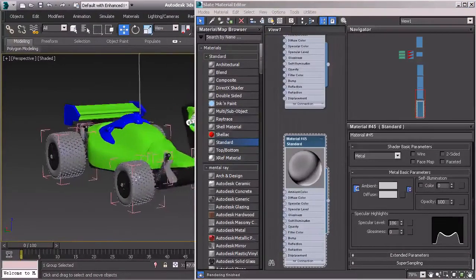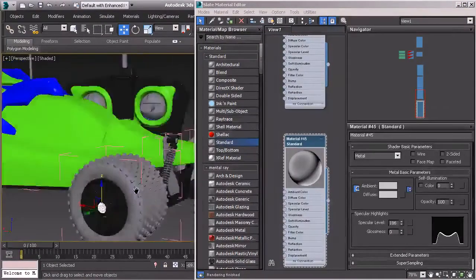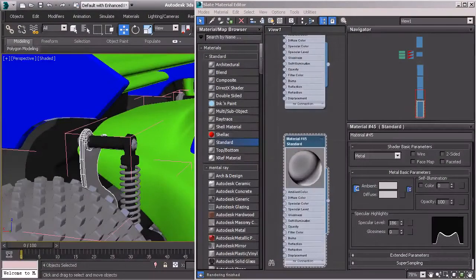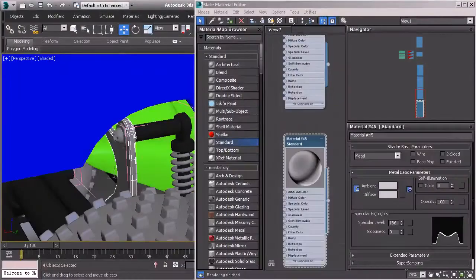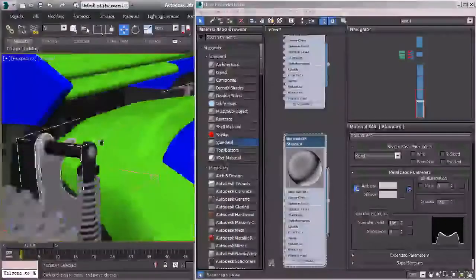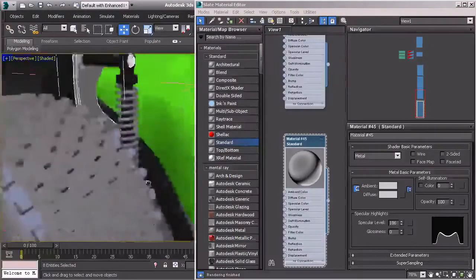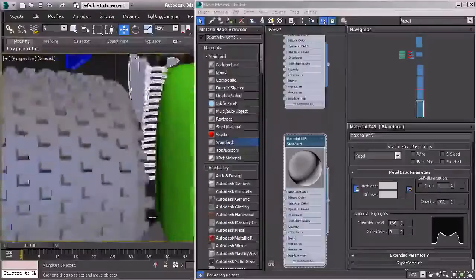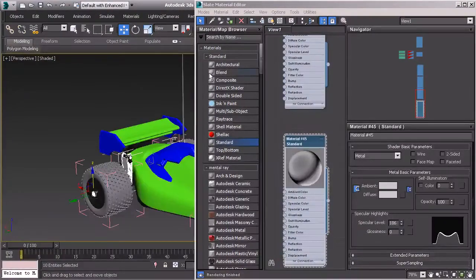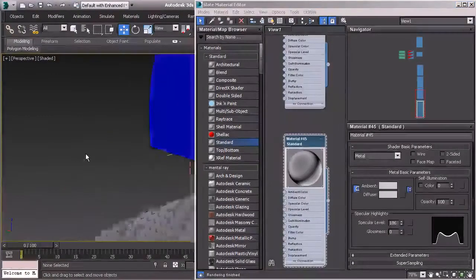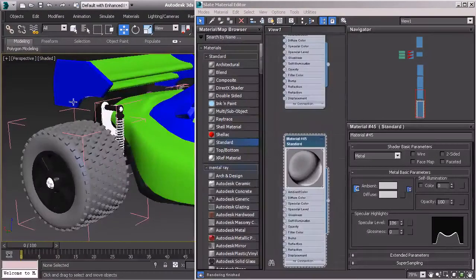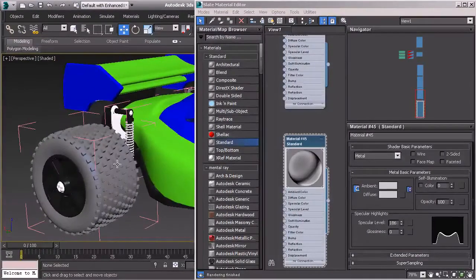So with something like this, I could select all of my objects that are supposed to have that metal material. In this case, it's going to be my connector and all my screws and washers. Okay, and you can apply those to this. I'm going to go ahead and just select one set here, and then you can go through and put those materials on there if you like, and we'll assign that. And there we go. So now we have that material, and it looks a little off in here. Whenever it renders, it's going to look a little different, so just be careful of that.